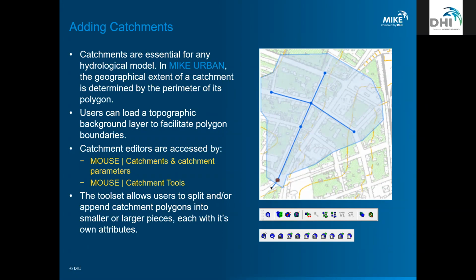Urban is in an Access database, and that is where you will find all the links for where the tables and editors are coming from. So in there you can trace the path to which specific attributes you want. You can edit it in there, which is a lot of times easier if you're doing mass changes. And that's where you will edit the data and import it from. So if you have questions specifically about the import wizard and importing data, feel free to contact me and we can go through that together.